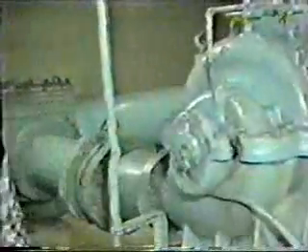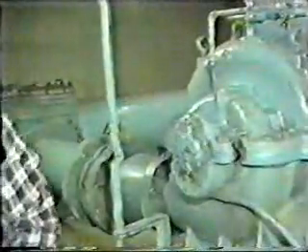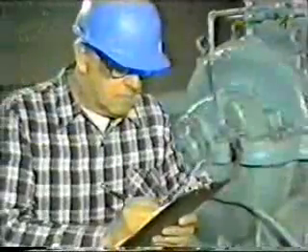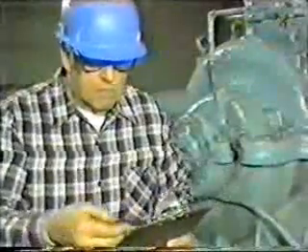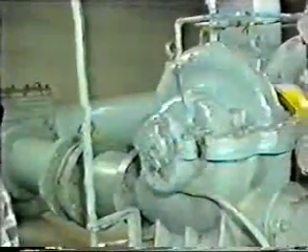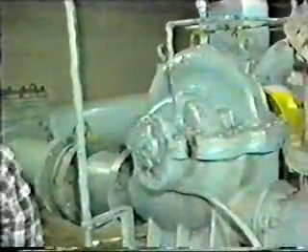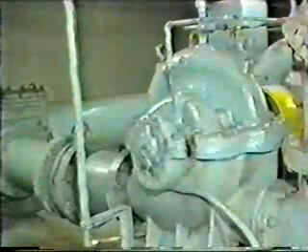The temperature has increased slightly since the operator last took a reading, but it's still within the acceptable range and doesn't warrant shutting down the pump. If the temperature did exceed operating limits specified by the manufacturer or facility, you'd have to shut the pump down to protect it from damage. Of course, it's helpful to be able to observe the equipment in operation, but it's not always possible since operating equipment, when it's malfunctioning, could damage the equipment.